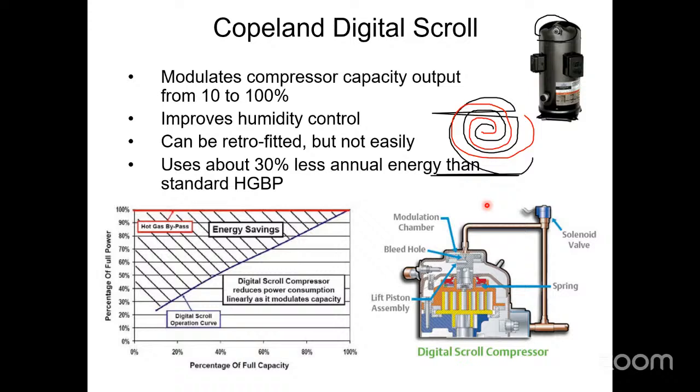It's actually a really effective way of doing so, and it can turn down to lower capacities than we can turn down to with an inverter. So from a pure control standpoint, it is better than an inverter compressor. However, if you ever heard one, it can be an annoying noise. That's the knock on it. That's the negative. I'm not good at making noises. It's like going to the auto mechanic and you're trying to describe the car noise. I'm not good at it, right? But it's making that grinding type noise that people don't like.